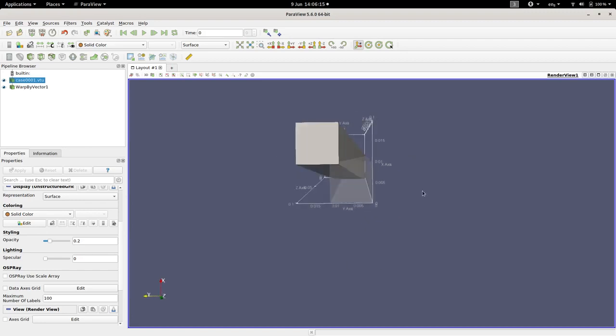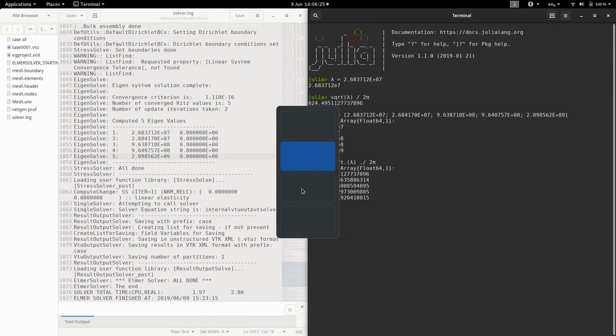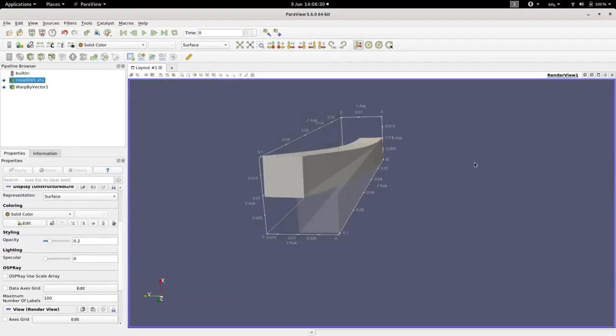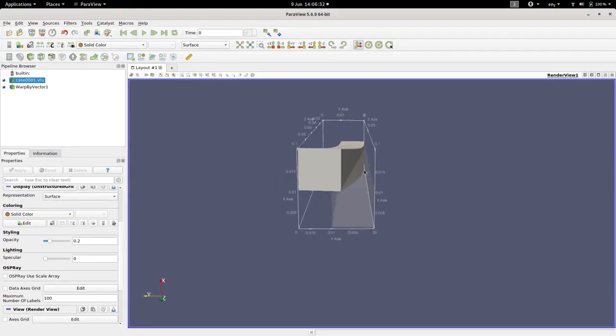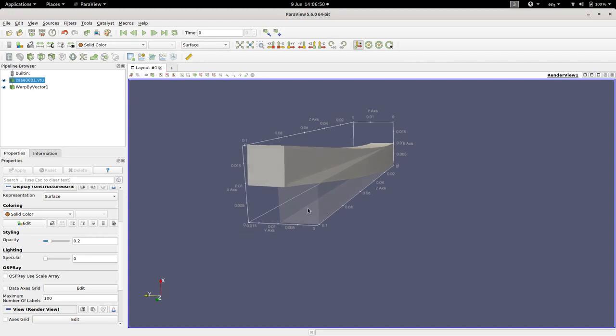So if we had to drive this metal bar with a force at exactly this first resonance frequency, which was 824 Hz, we will pretty much multiply this shape by a sine wave, so we will see this bent shape pretty much moving around the rest position.